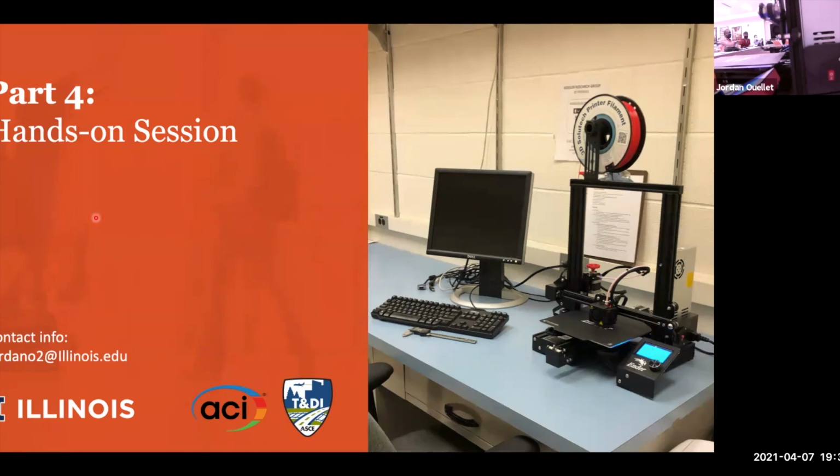How do I remove the base? So how you remove the base, you can use some pliers to rip and cut that material. You can use a sanding paper. You can use these rotating Dremel tools to remove the brim that you might have printed around it. Same thing for the supports. Usually pliers are useful. You can heat them a little bit with a torch, a heating gun, or even a soldering iron, and then you melt where you want to remove your support. So these are all options you can do.